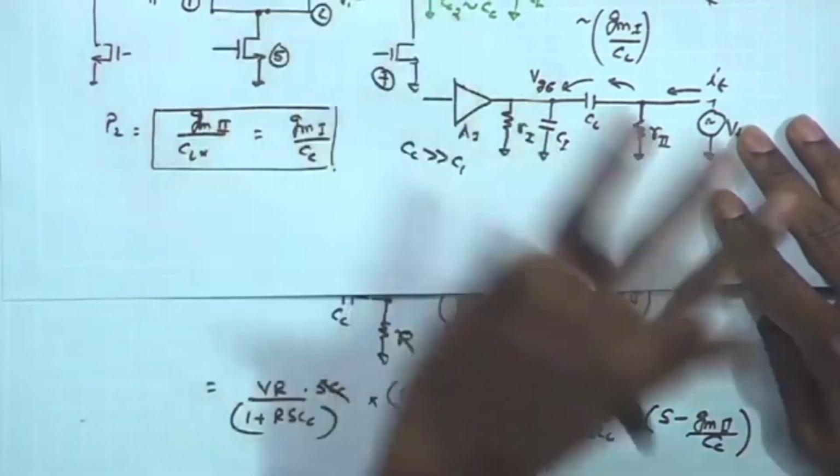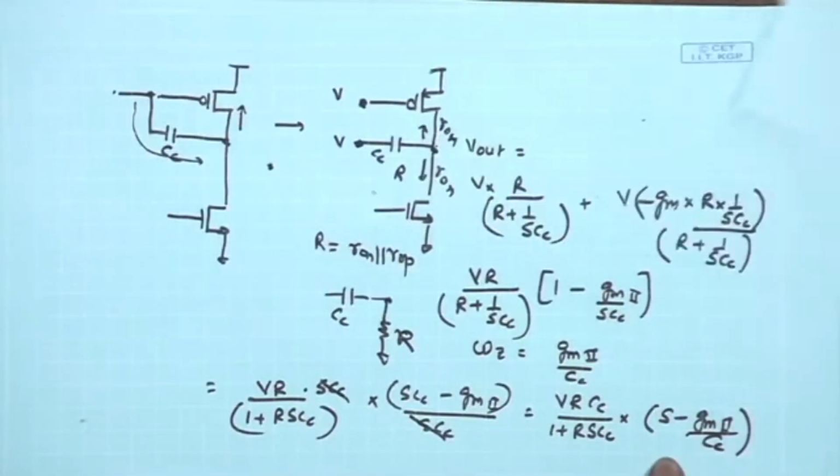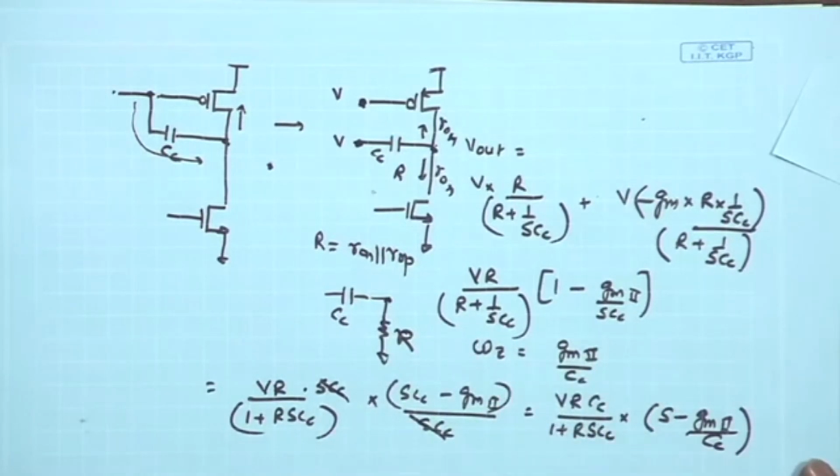And if we assume that it is also higher than the second pole, we are having a 40 dB per decade slope before this 0 comes, because the earlier two poles are going to contribute overall 40 dB per decade decay in the gain before this 0 approaches.